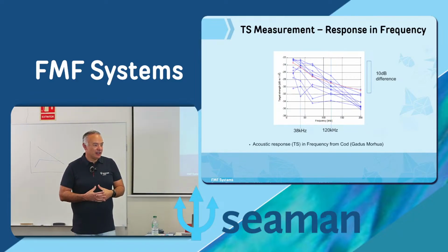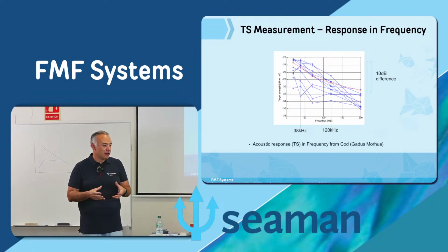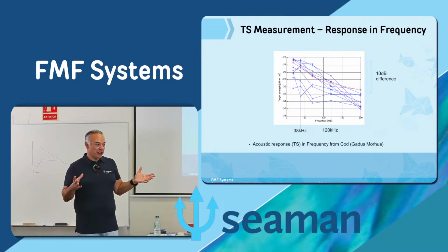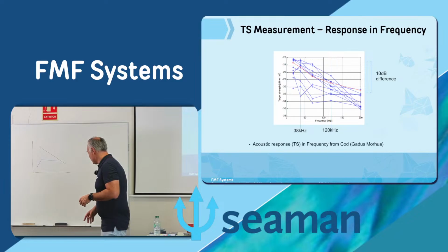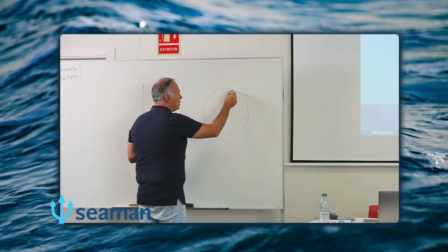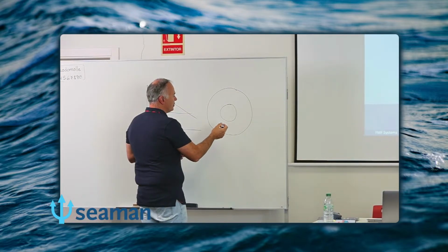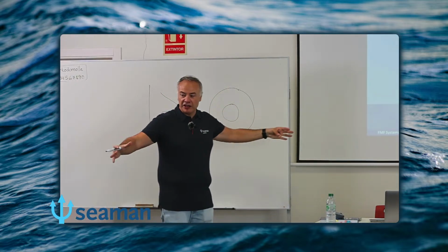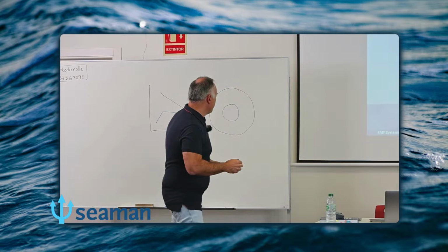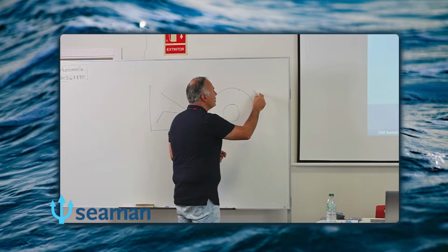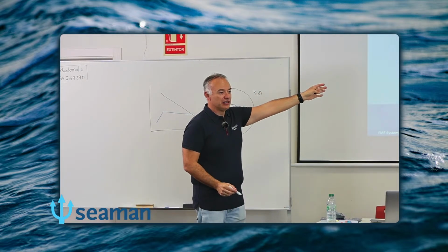In the past, there were some dual systems that used only a single frequency. You can have dual beam on 38 kilohertz, for example, only in that frequency in CW, and because they use a transducer with two ranges of elements. They use a small transducer in the center, same frequency. Then they extend the elements at the edges and they create different angles with the same frequency. So if you have this kind of transducer in 38, then it's okay for the cod.